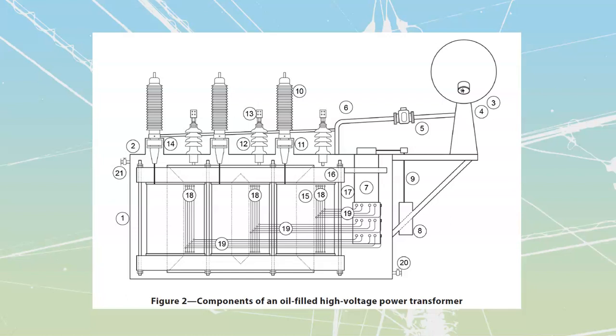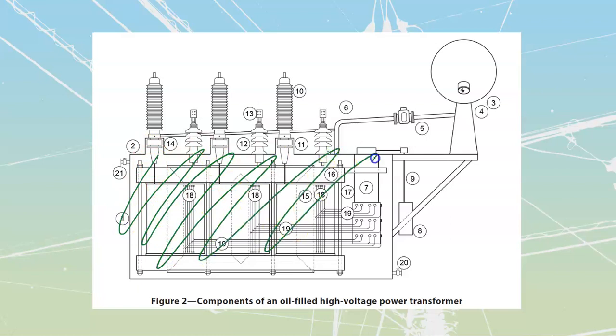So the oil is going to be denser, which means it's going to carry heat away more effectively. And so what we're going to have inside of a transformer is a sealed can that is going to be filled with oil or other types of liquids. It's going to be similar to the setup that you have inside of your vehicle radiator. For those of you that turn wrenches on your own vehicles, you know that you're going to have the entire system over here that's going to be filled with oil,